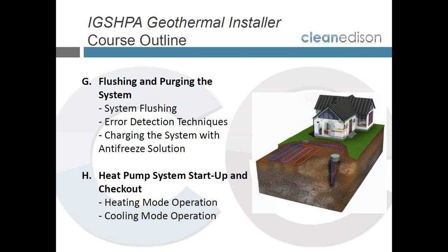Then we have a heat pump system startup and checkout where we look at the heating mode and cooling mode operations, and we'll go through a verification of installed performance Excel worksheet so that you can see that the electricity being used by your heat pump is the small amount necessary to keep it very efficient.